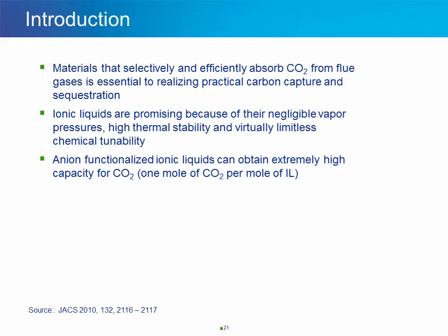Quoting directly from this article: the discovery of materials that selectively and efficiently absorb CO2 from flue gases is essential to realizing practical carbon capture and sequestration. Ionic liquids are promising in this regard because of their negligible vapor pressures, high thermal stability, and virtually limitless chemical tunability. Here we show how we can obtain extremely high capacity, up to 1 mole of CO2 per mole of ionic liquid, in anion functionalized ionic liquids.